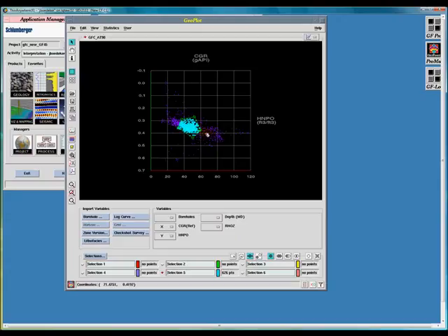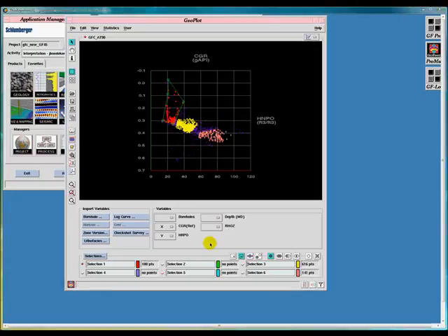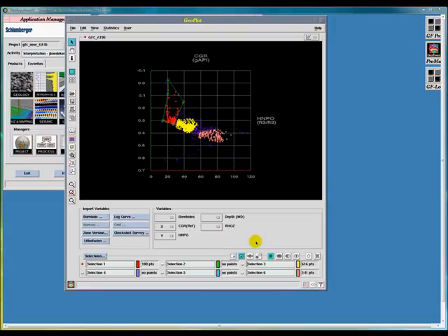To edit the polygon, select the Edit Polygon icon, and while holding down the left mouse button, move a vertex to its new location. If the left mouse button is clicked on one of the rectangle polygon lines and not on a vertex, then a new point is added to the line at that location. If the left mouse button is still held down, the new point can be moved.